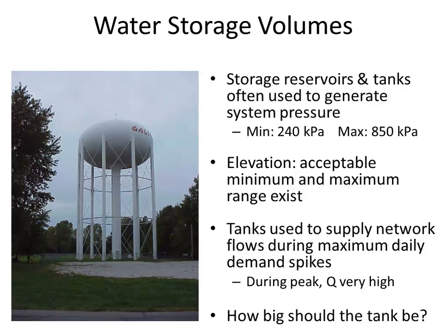Another function of the reservoir besides pressurizing the network is to provide a little bit of a buffer during the peak demand times. When demand is very high, then the flow rates are going to be larger for the network than can be supplied by the spring that's used. The water is actually coming from an artesian well up on the top of the hill where the flow rate out there is defined as your average daily flow.